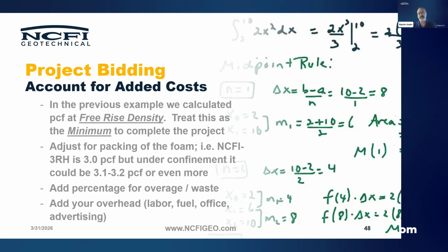And that foam, we shot it with the lid on top of the concrete. And then we lifted. And so I know that foam densified beyond that 2.8 pounds or 2.5 pounds per cubic foot. I know it had to, because that lower density would not have overcome 72 tons of weight above it.